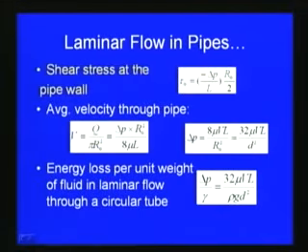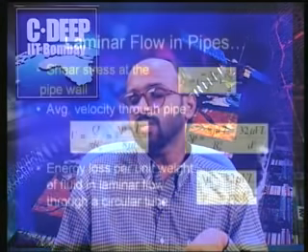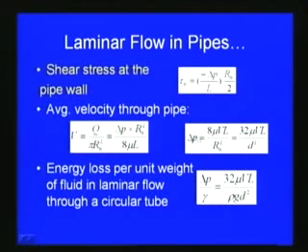And then, as in the earlier case, we can get the shear stress tau 0 is equal to minus delta P by L into r0 by 2. That gives the shear stress at the pipe wall, and then we can also find out the average velocity through the pipe. The total discharge is known, and if you divide by the area of cross section we get the average velocity. In this particular case we get V is equal to delta P into r0 square by 8 mu L, and from one of the parameters obtained, like velocity, we can find out other parameters.